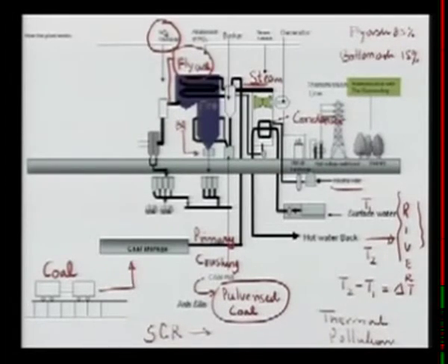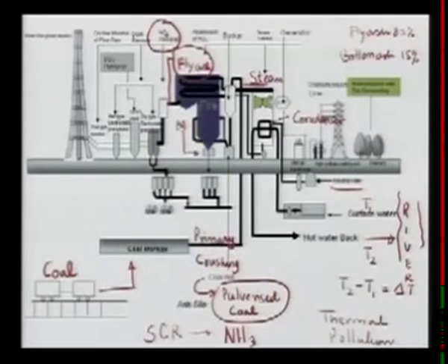But at this stage it's reasonable to know that the NOx must be controlled, because NOx is a serious problem. Mostly what you use in selective catalytic reduction is ammonia. Selective reduction is based on using ammonia to reduce the NO2 or NOx into nitrogen and oxygen. The first part you do, but let's not forget that we still have the fly ash. So once the NO2 is controlled, then you can bring it to the control of the particulate matter. So all the fly ash is controlled here.